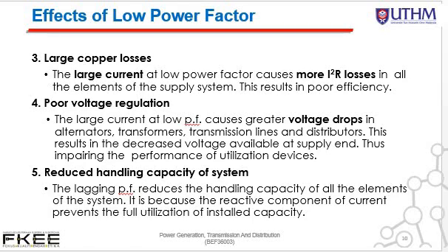Apart from that, a system with poor power factor will also possess poor voltage regulation. In such a condition, the change of the output voltage is high and results in decreased voltage available at the supply end, thus impairing the performance of the utilization devices. Having a low power factor will also reduce the handling capacity of a system.